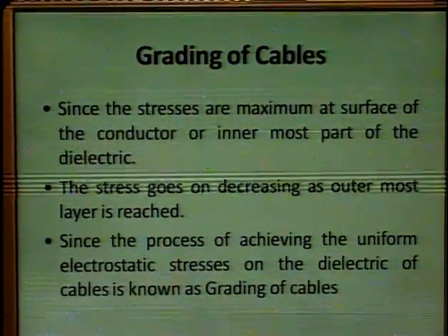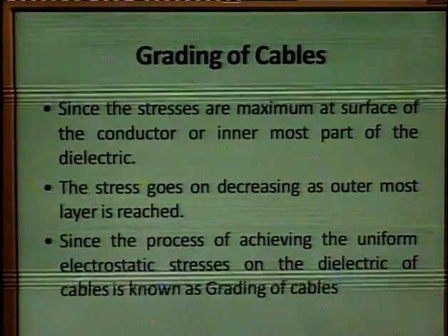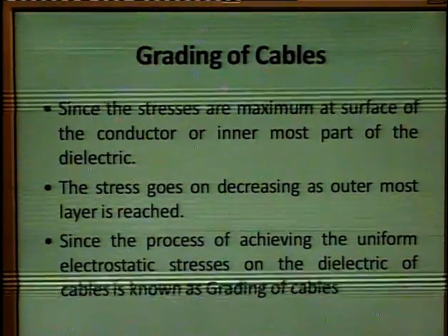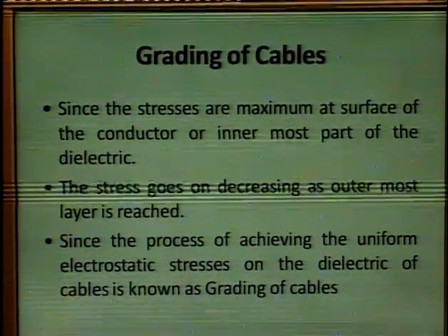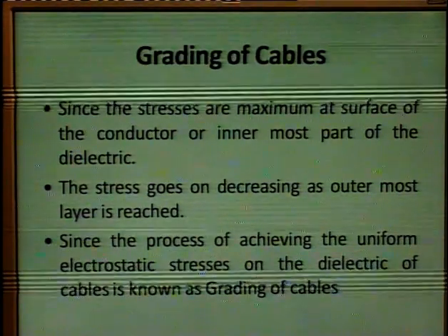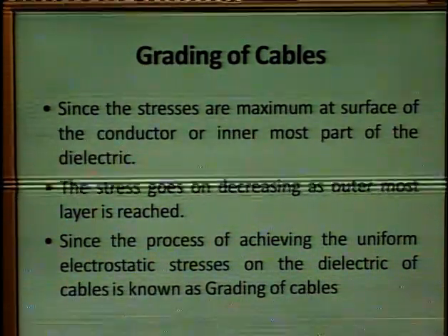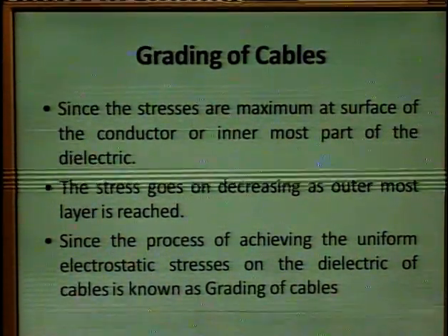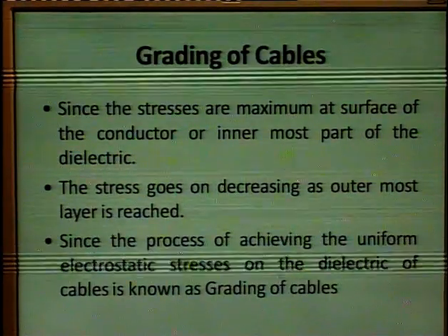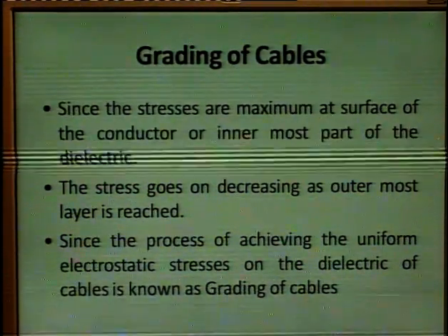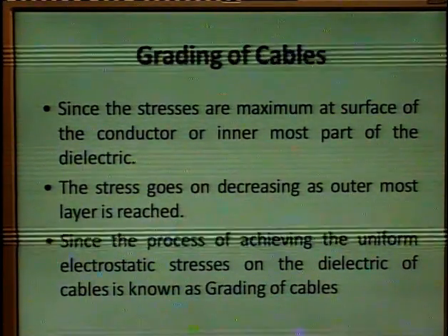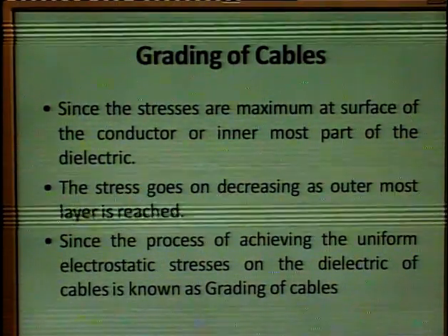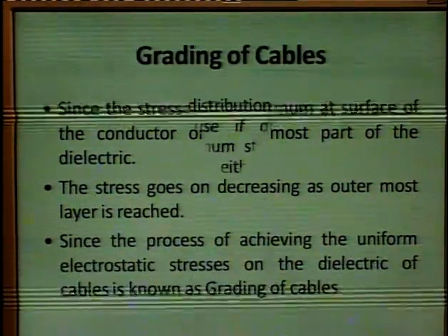Then we have the grading of cables. Since the stresses are maximum at the surface of the conductor, or the innermost part of the dielectric, the stress goes on decreasing as the outermost layer is reached. The process of achieving uniform electrostatic stress on the dielectric of the cable is known as the grading of the cable.